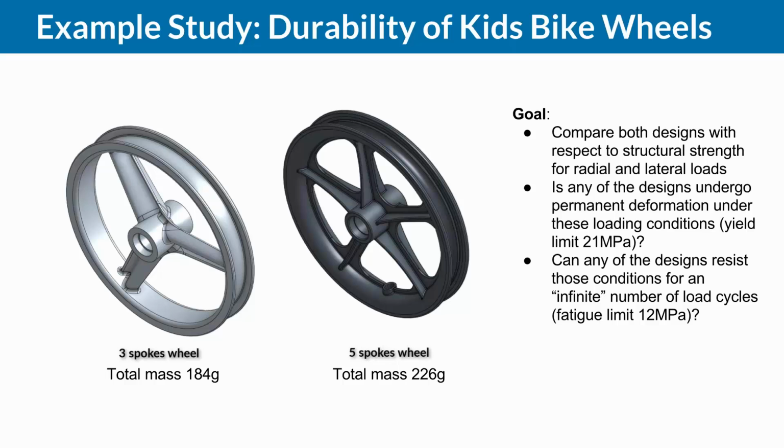If you have a fatigue limit for your material, it basically specifies that if your load cycle, so a single loading, doesn't exceed the stress of this value, then you can have an almost infinite number of load cycles, and it will not degrade the strength of your material.